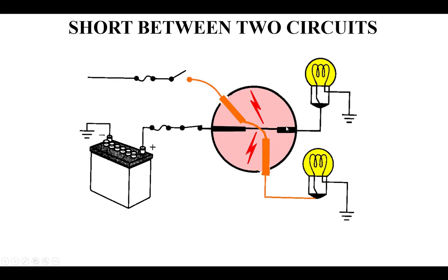But if this wire and this wire are running together side by side, which happens in a car, and maybe this is going out to a trailer, or going to your taillights on the bed of a truck. Anyway, these wires run together. Over time, they may have come loose and are rubbing, vibrating against each other, maybe vibrating against a part of the chassis. And the insulation wears off, and the conductors inside eventually touch.